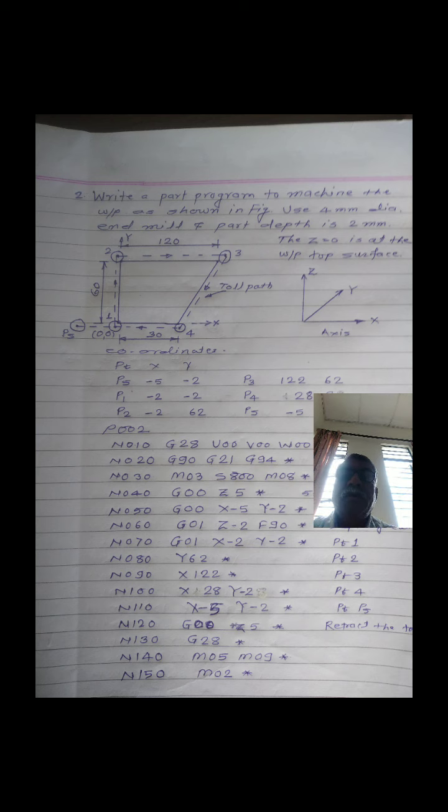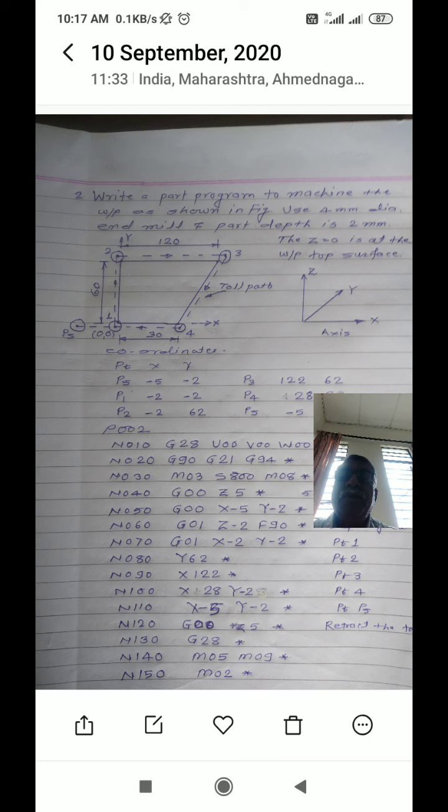First you have to locate the reference point or workpiece 0, which is at the corner of the workpiece as shown in figure, that is X0 Y0 Z0, that is the 0 0 point. From this point you have to measure all the coordinates of the points. It is at the corner of the workpiece.